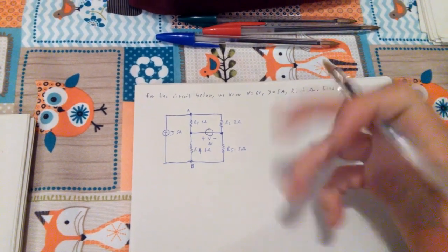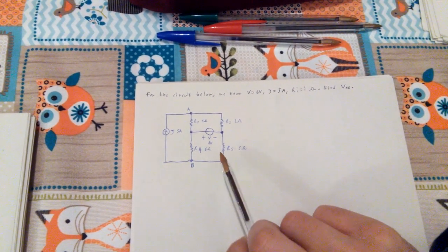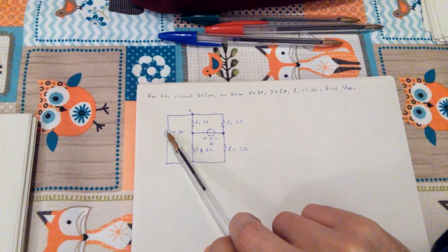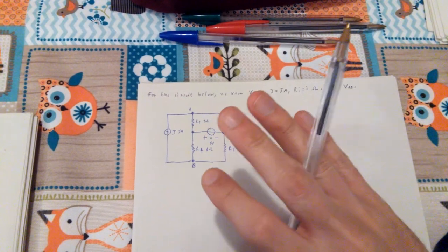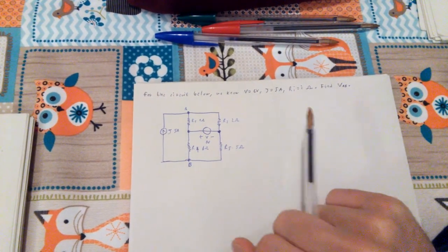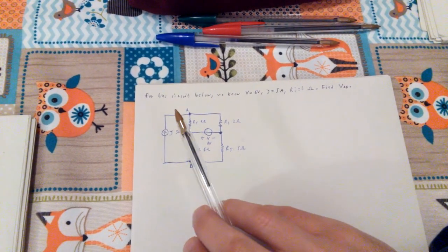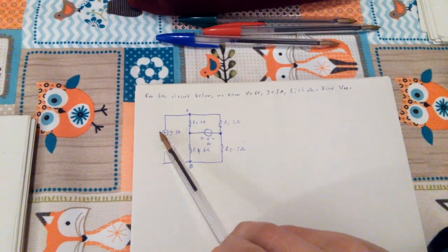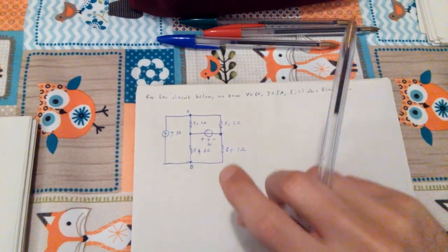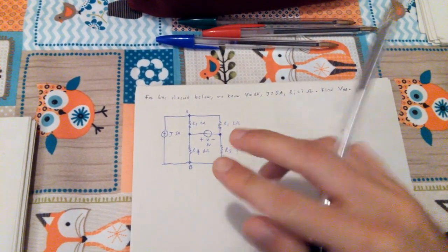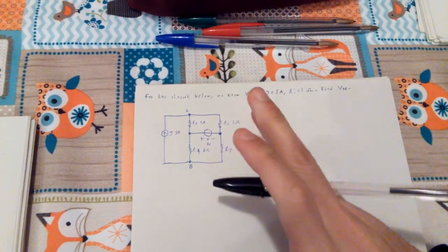Well, you can kind of guess, but anyway, whenever you have two generators, generally one of current and one of voltage, it's almost always the case in which you're going to do what I'm going to do right now, just like I did before: consider the circuit without one of them, and then the circuit without the other one, and then sum the effects and get the final result, which is exactly what I'm going to do.